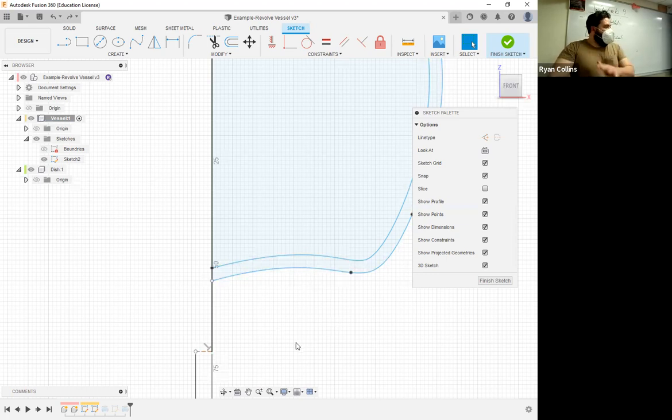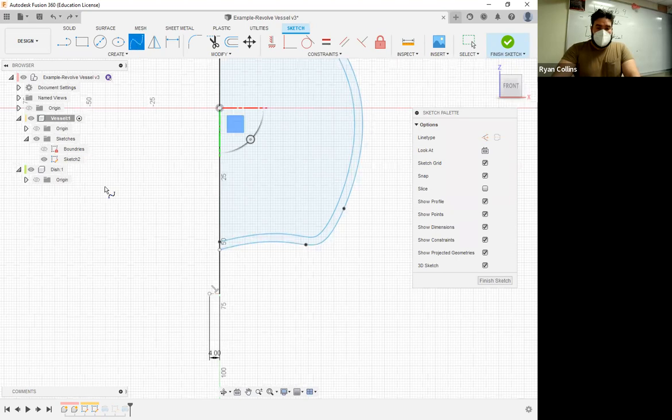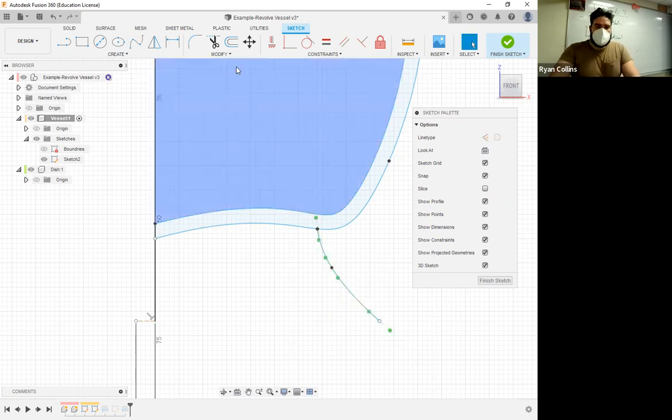Same diff. I want to add a foot to this. So what I'm going to do, simply draw another line. I'm going to make sure it connects somewhere. Before I mouse over the existing sketch, my cursor is a plus sign in the square. Mouse over, changes to an X. Good. I want that to be somewhere on this line. We'll go to right there. Why not? And I'm just going to draw outward a little bit. I'm going to make this kind of a nice little curving foot.